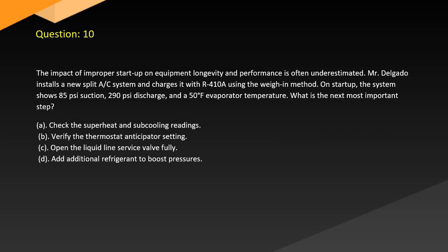Question 10. The impact of improper startup on equipment longevity and performance is often underestimated. Mr. Delgado installs a new split AC system and charges it with R-410A using the weigh-in method. On startup, the system shows 85 psi suction, 290 psi discharge, and a 50 degree evaporator temperature. What is the next most important step?